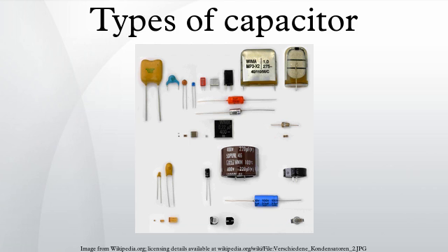Electrolytic behavior from storage or disuse. Electrolytic capacitors with non-solid electrolyte are aged during manufacturing by applying rated voltage at high temperature for a sufficient time to repair all cracks and weaknesses that may have occurred during production. Some electrolytes with a high water content react quite aggressively or even violently with unprotected aluminum. This leads to a storage or disuse problem of electrolytic capacitors manufactured before the 1980s. Chemical processes weaken the oxide layer when these capacitors are not used for too long. New electrolytes with inhibitors or passivators were developed during the 1980s to solve this problem.